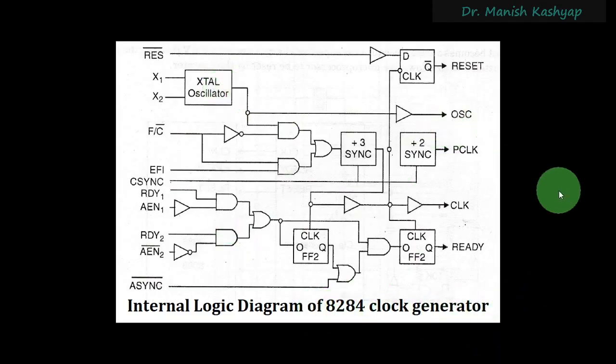So this is a brief description of why we have some signals which are edge triggered, because we have a D flip-flop. If you have some level triggered signal, then you might have a flip-flop in the circuit which is not a D flip-flop, but a flip-flop which can be level triggered. These are constraints which essentially come from the flip-flops that you are using, right?